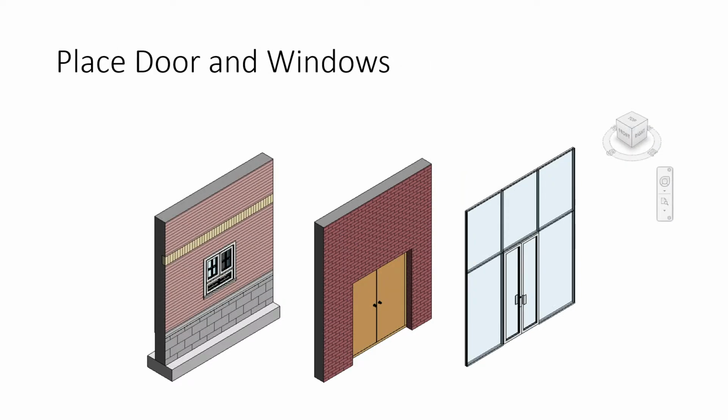Once you learn to draw the wall, the next step is to learn how to place doors and windows and how to modify the width and height, how to load a new door style, window style. So that's important. This is a nested family, or what do we say? It's a host family, we can say. Okay, wall is the host. Without wall, we can't place any door or window. Okay, and it's a loadable family. You can save the door family, window family in a library in another folder outside Revit. You can save so that they are called a loadable family.